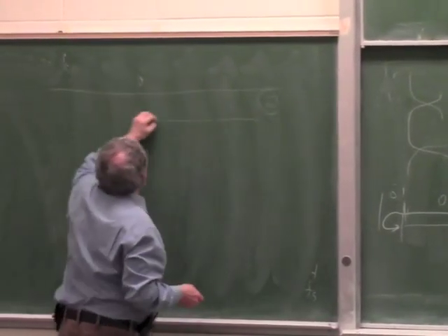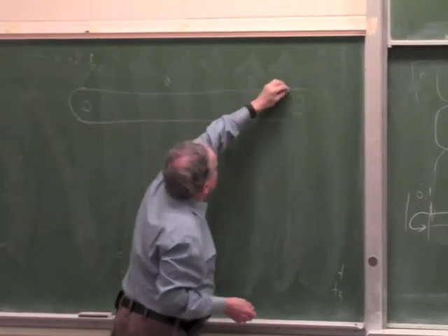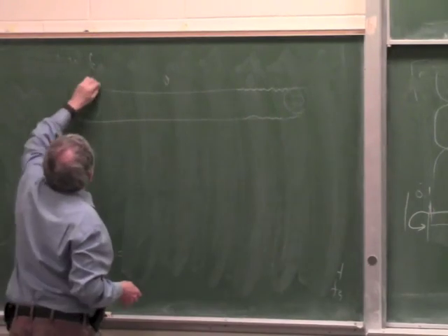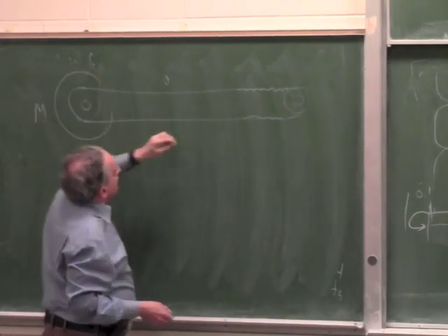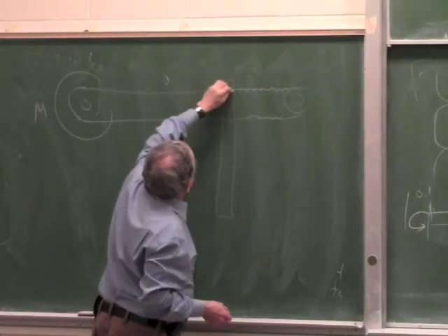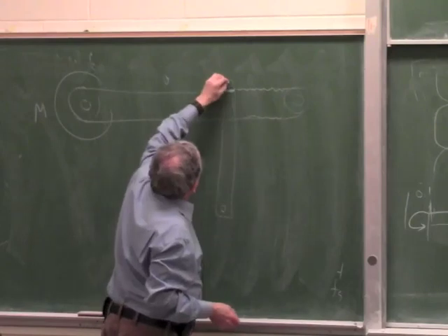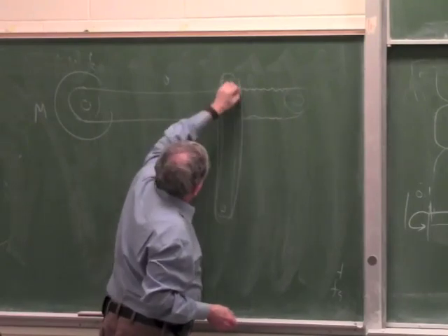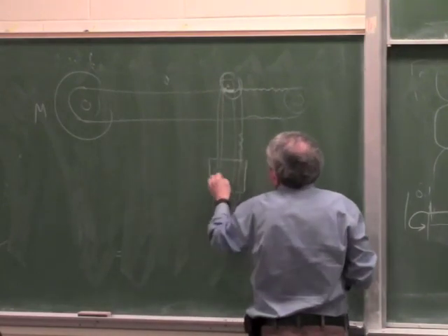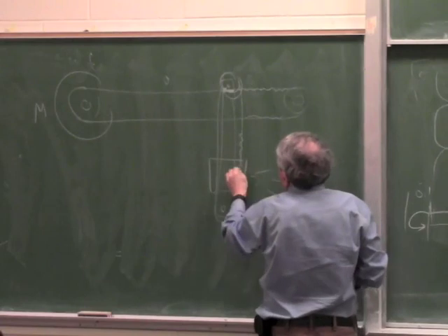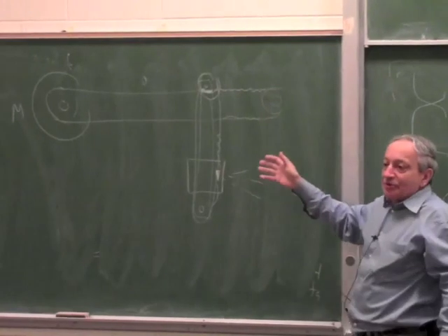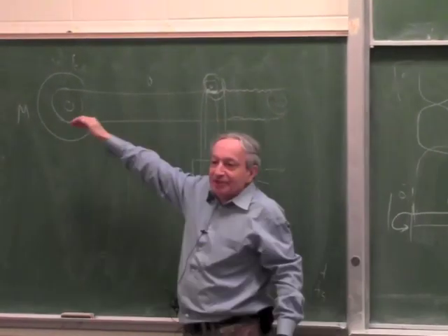So a good way to build it, you take a timing belt, connect it here to a motor, and then you attach the cross slide to the timing belt. And here you'll have the same. You'll take another timing belt with a motor, and on this you'll have the spray gun attached to the timing belt. And this way you can do it with rotary motors. You don't have to make actuators which can move 5 meters.